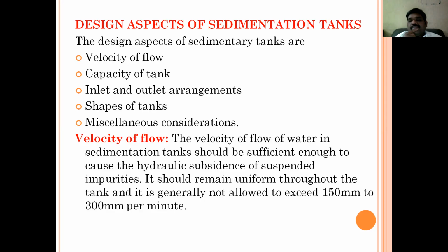In one word, the velocity should remain uniform throughout the tank, and normally it should not exceed 150 mm to 300 mm per minute.